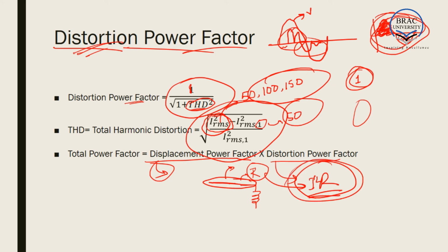As a result, we want the current to be as low as possible. We want the current to be only the current that the load is consuming, and not the currents caused by the imaginary components. So we want our imaginary components of the current to be 0, or as close to 0 as possible.